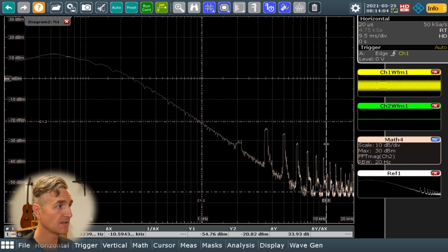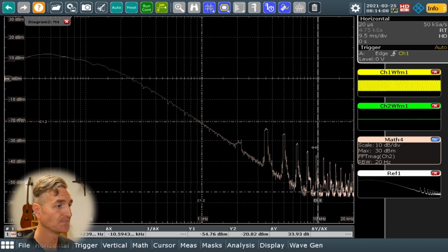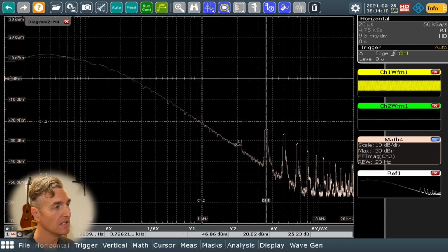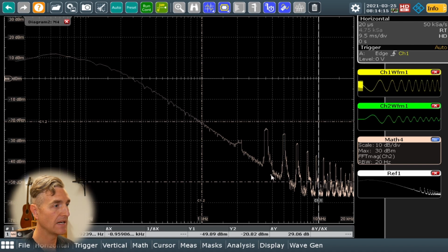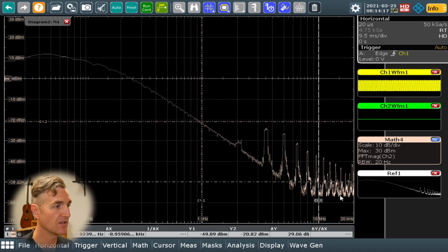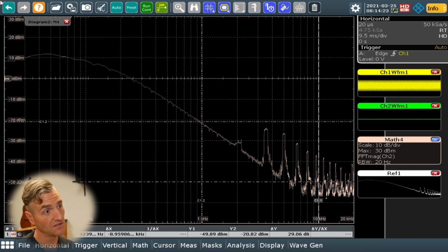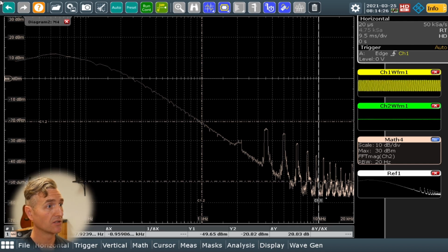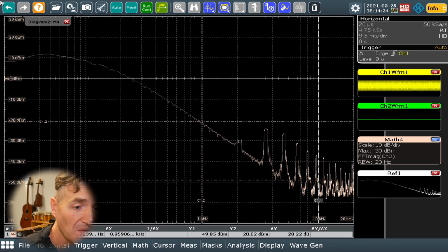But I do have a delta of 33 dB, so I don't quite have that 50 dB of filtering through here. And most of that is because I'm kind of running into the noise floor of my probing and my signals. So this is a place where measurements really struggle against simulation when you have to deal with actual physical connection. But be that as it may,